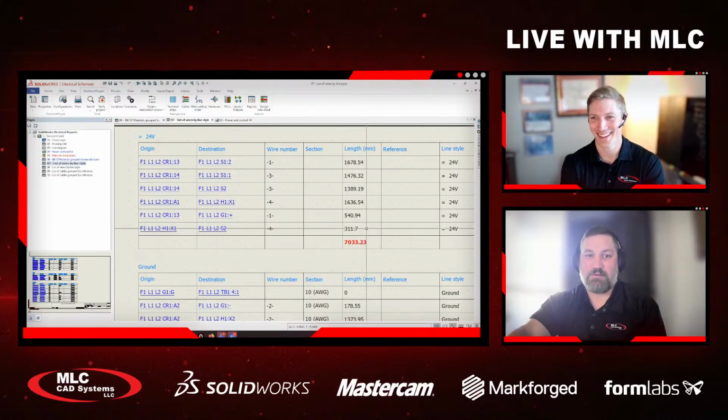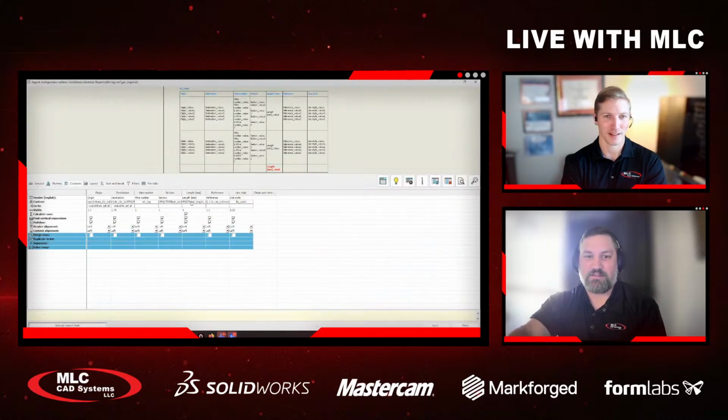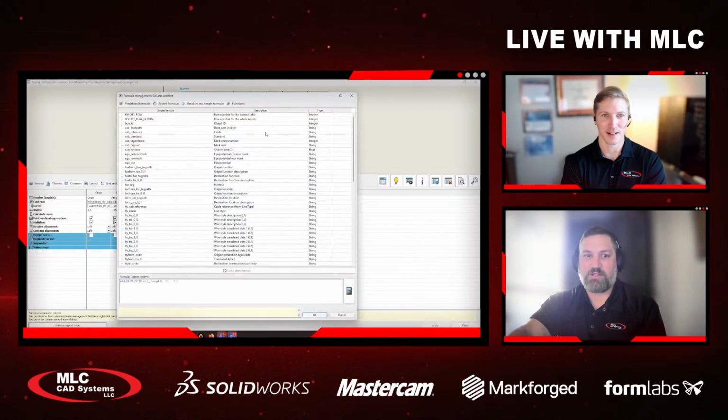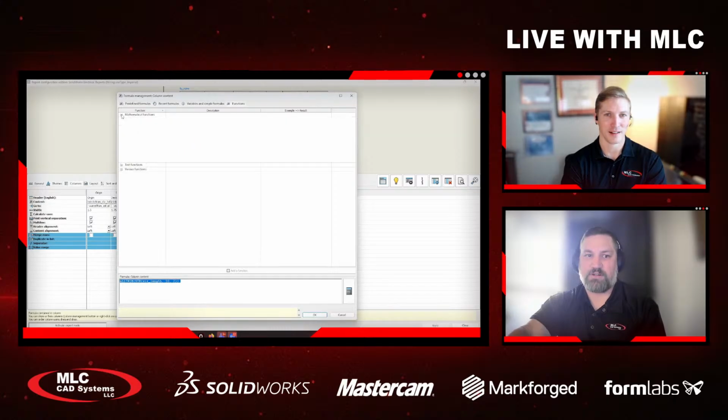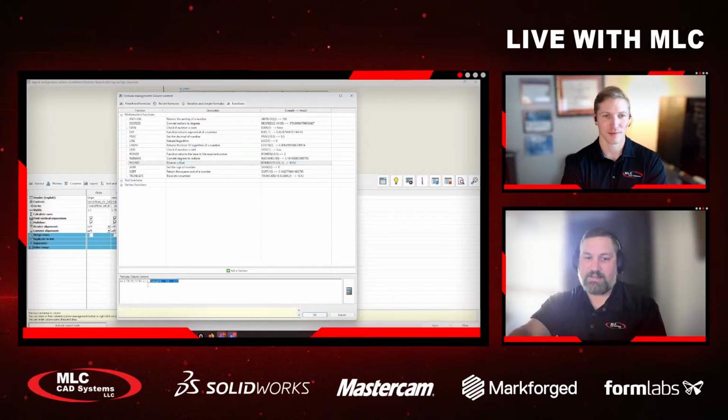So that's something that I would always do. I would go in here to this report configuration, and you can round because these lengths are, as you saw, right on the money. When you hit this formula button, there's some functions that you can do over here, some mathematical functions, and I would always round it up. So round it up, and then you can even add 10% by multiplying. And that's exactly what I would do.